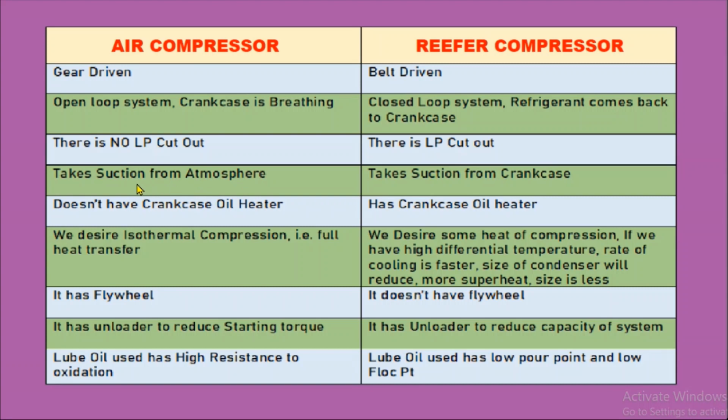As we discussed earlier, the crankcase is breathing, hence it takes suction from the atmosphere, and hence the air compressors are breathing from the atmosphere. In reefer compressors, they take suction from the crankcase since the refrigeration gas is coming back to the crankcase. Air compressor does not have a crankcase oil heater, while you will find the crankcase oil heater in reefer compressors.